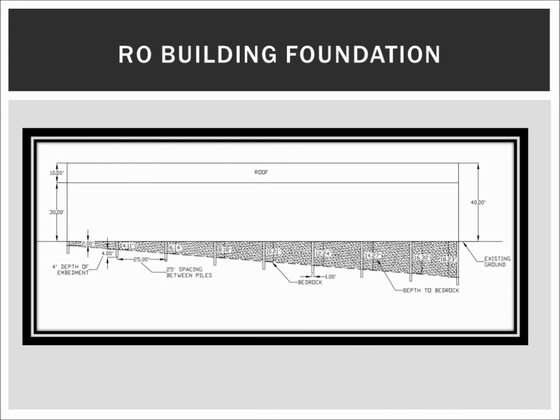The piles will be end-bearing piles with a diameter of 1 foot and embedment depth of 4 feet into the bedrock. To reduce the damage that the piles incur during construction, we will first pre-drill to the depth of embedment and then use concrete to solidify the pile into the bedrock.